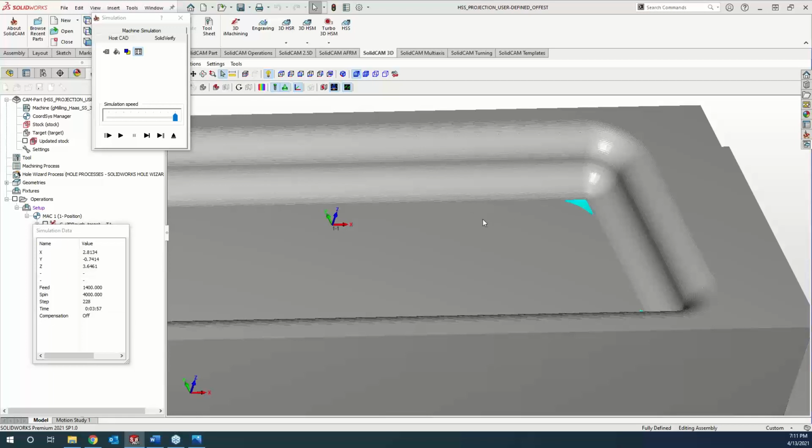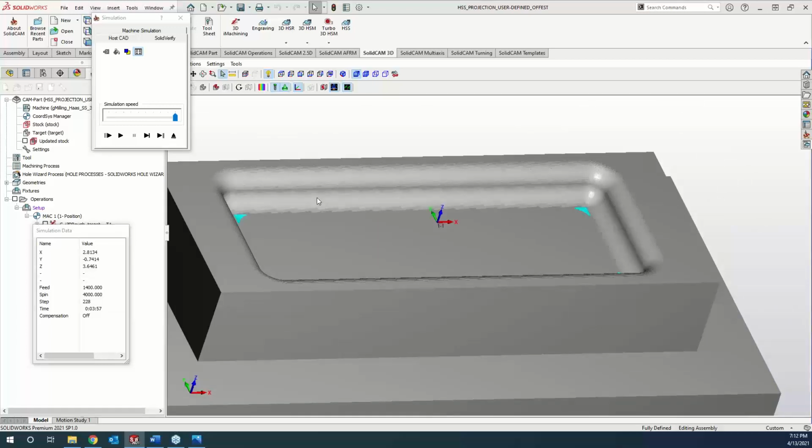floor area. And the reason why I say that is because when we're doing this floor process right here, we're doing a nice pocket routine, getting a nice pretty finish in there, and we don't want to have any tool drag marks as we're going to the next section. So now we're just working on those little areas right there, keeping it there, and then bouncing over, going up to the safety level for you